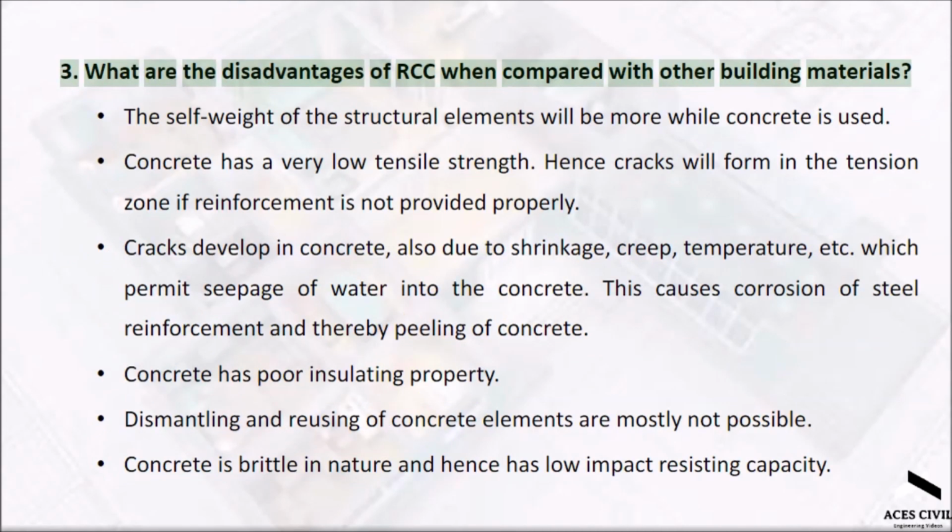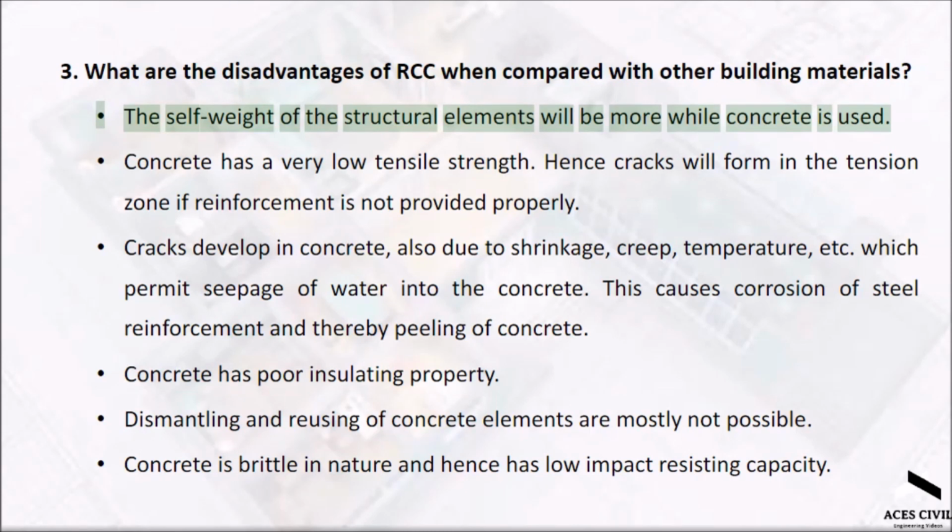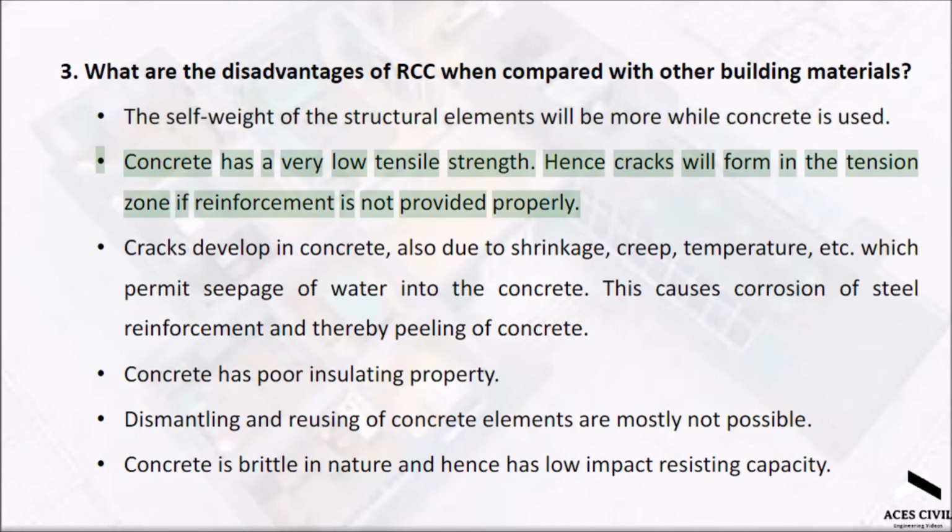3. What are the disadvantages of RCC when compared with other building materials? The self-weight of the structural elements will be more when concrete is used. Concrete has a very low tensile strength. Hence cracks will form in the tension zone if reinforcement is not provided properly.